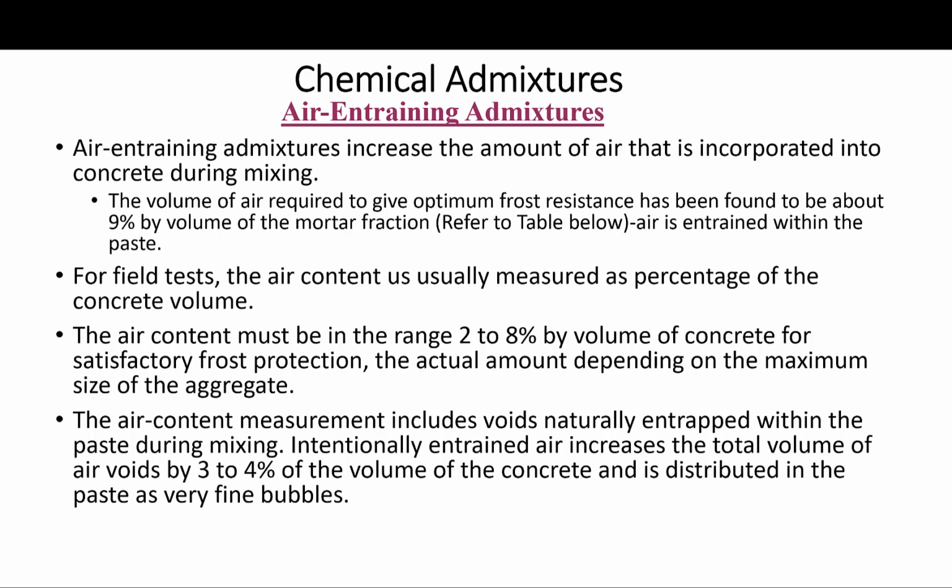Typically, and for routine field tests, the easiest quantity to measure is the amount of air expressed as a percentage of the concrete volume. The air content must be in the range of 2 to 8% by volume of concrete for satisfactory frost protection, the actual amount depending on the maximum size of aggregate being used, the coarse aggregate that is.